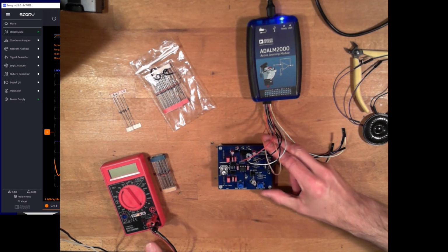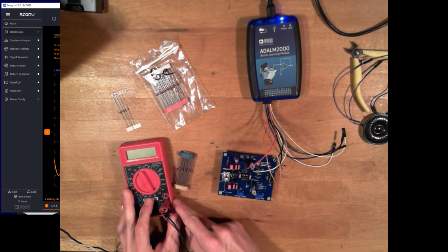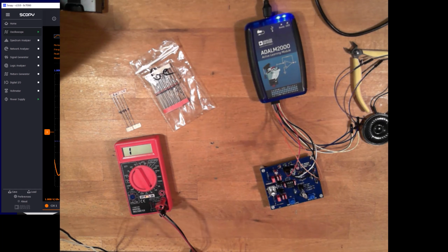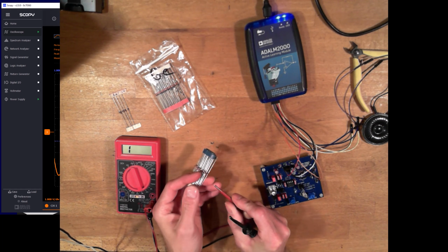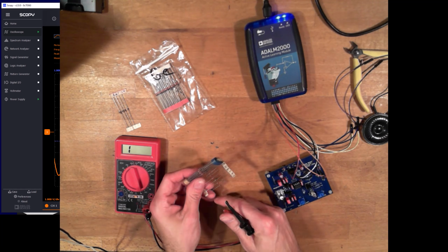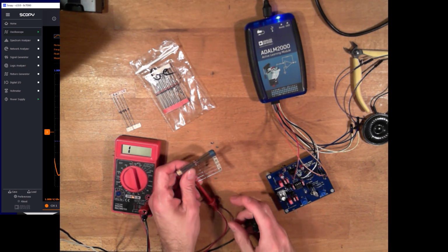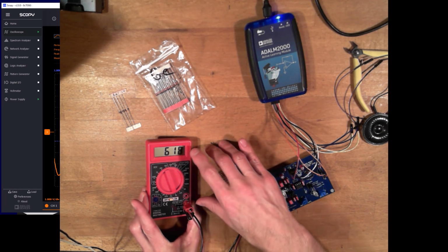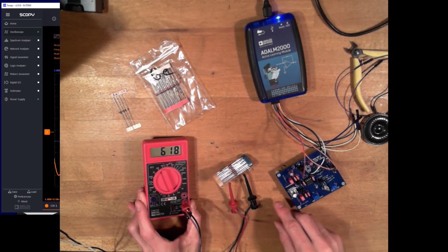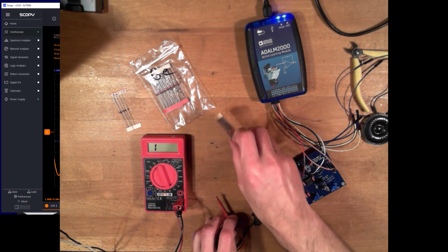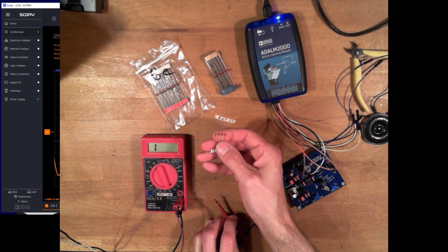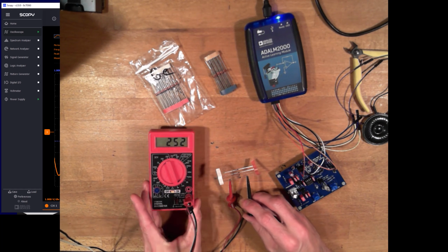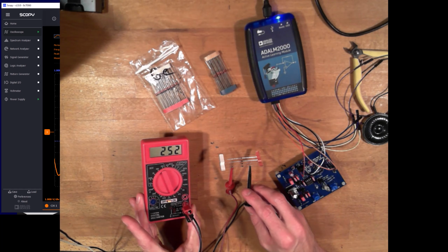And then just to get a measurement on that, I've got my handy little Harbor Freight meter here. Let's measure the forward drop of a plain old silicon diode. Okay, so we put the positive, let's get one diode out here. Yes, these are my 1N4148s, on the anode and then on the cathode. And we get about 0.6 volts on the forward drop on the diode with whatever test current this meter sends through. And then I found in my box o' diodes some BAT54s. So these are Schottky diodes. And if I measure the forward drop of this guy, it's about 300 or 250 millivolts, so considerably lower.